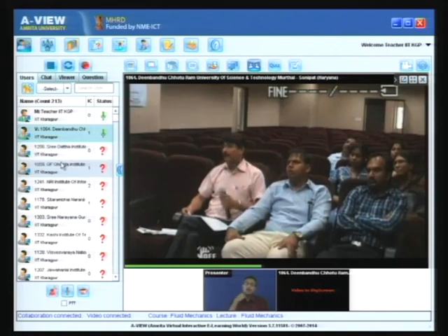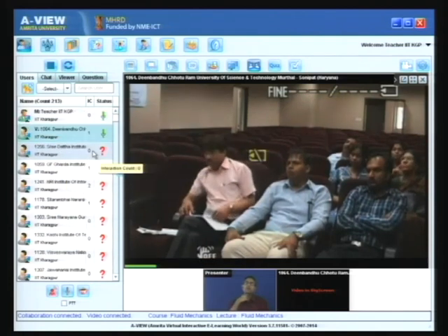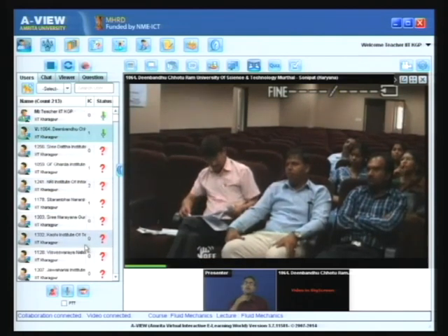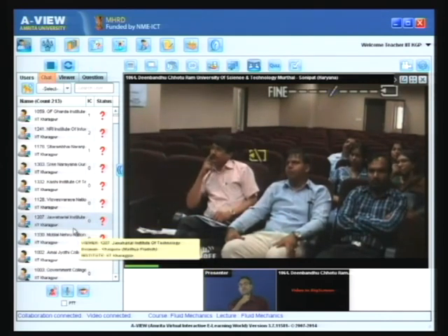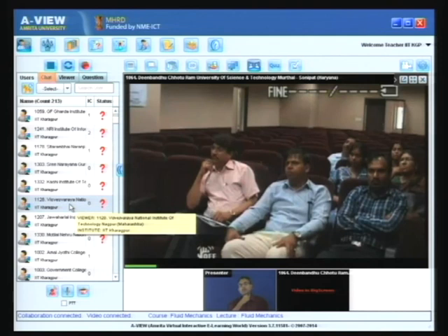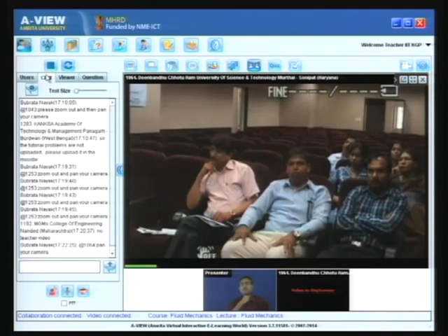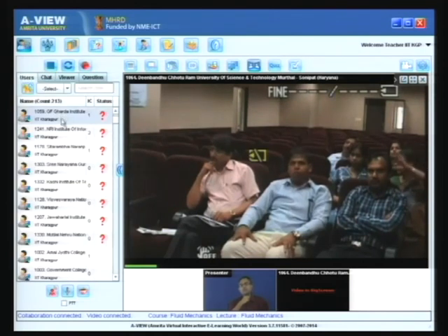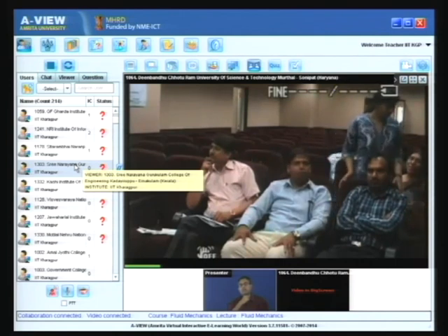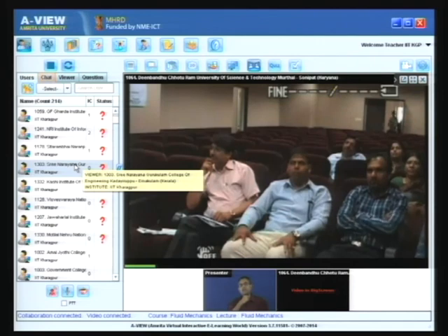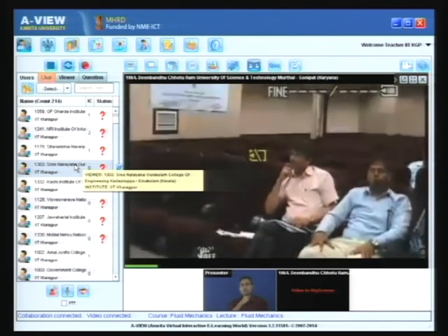See, across the shock wave there is a release of accumulation of disturbance. Because the disturbances are released, there is a discontinuity in the Mach number. From supersonic flow it becomes subsonic flow, and this gives rise to discontinuities in properties, and because of the discontinuities in properties there are strong velocity gradients also, and because of these strong velocity gradients an irrotational flow can become a rotational one.